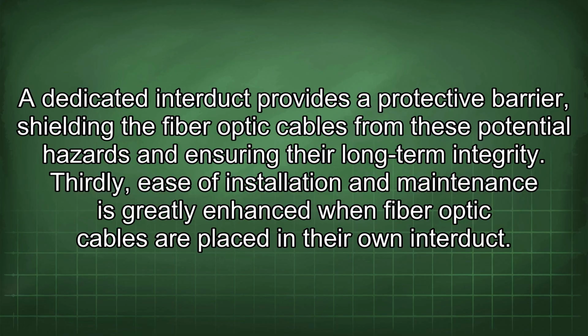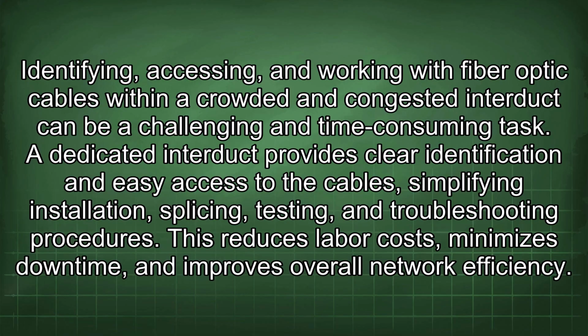Thirdly, ease of installation and maintenance is greatly enhanced when fiber optic cables are placed in their own interduct. Identifying, accessing, and working with fiber optic cables within a crowded and congested interduct can be a challenging and time-consuming task. A dedicated interduct provides clear identification and easy access to the cables, simplifying installation, splicing, testing, and troubleshooting procedures. This reduces labor costs, minimizes downtime, and improves overall network efficiency.